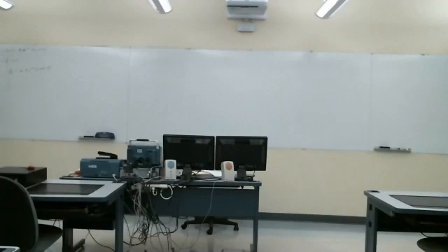We're going to plug all this into that equation. But the other thing we want to do is, we typically use cosine as our reference, especially when we go into the phasors. So we want to represent the sine as a cosine. The sine is just the cosine shifted to the right, minus pi over 2.